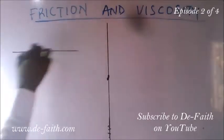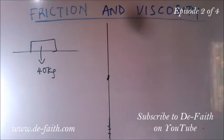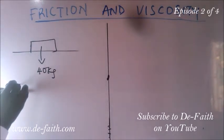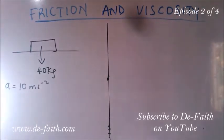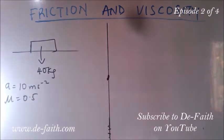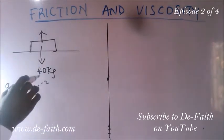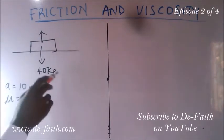We have a body which is on the ground of mass 40 kg and is given an acceleration so that it will move from one place to the other. So we're having the acceleration to be 10 meters per second squared, and then the coefficient of friction here is 0.5. We have to calculate the force that's required to accelerate the body. Now what this means is that initially the body is at rest, and then it has a normal reaction which is equal and opposite to the weight, which is 400 Newton. That is 40 times 10, that's 400 Newton.